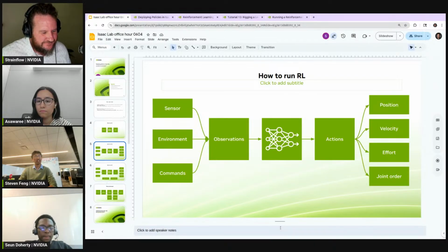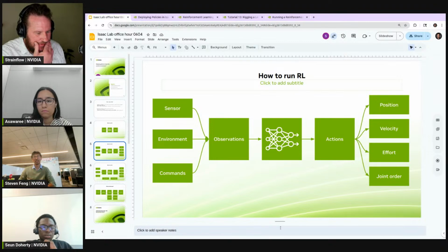Yeah. An example I could give you is that Isaac Lab policies require things like robot base velocity or robot positions. In Isaac Lab, we just call the articulation API and get, okay, now the robot's moving forward at 2 meters per second, but you don't quite get that data in real life. The way you would do it is to attach an IMU, an inertial measurement unit, to the robot. It can give you linear acceleration data, and then you have to compute the velocity from that linear acceleration and do some frame transformation to make sure it matches the simulator.